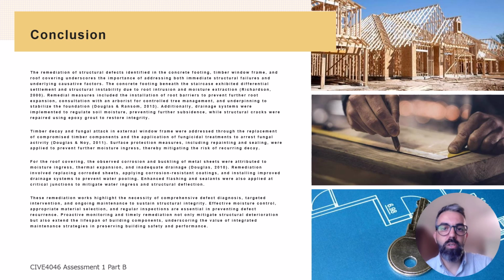implementing root barriers, consulting an arborist for controlled tree management, and underpinning to stabilize the foundation. Additionally, drainage improvements and epoxy grout repairs were suggested to address soil moisture regulation and structural cracks.